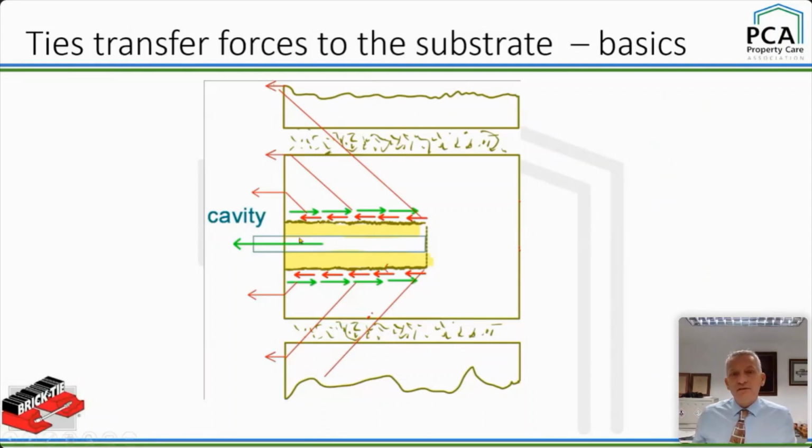The resin around that is in intimate contact with the sides of the hole, and it's fixing partly through adhesive action. But polyester resins, for instance, are not an adhesive, and that's what I use a lot of. But mainly because the hole is not smooth, it's got lots of indentations in it, and where the resin's in intimate contact with those indentations, we get a keying action. Okay, so it's holding mechanically. That creates a cone of resistance within the wall, and it shares the load over that big area. That's one of the good things I like about grouted anchors, because the entire internal surface area of that cylinder, if you like, that hole, is being mobilized in transfer of the load.